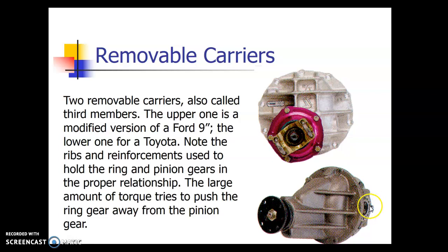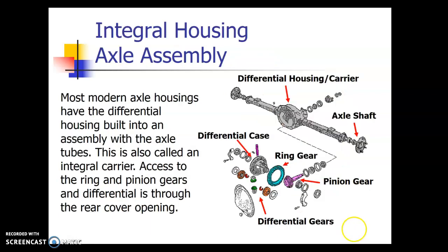Basically right here is where the axle comes in. This whole section can be unbolted from the axle housing, and then this is where the drive line comes in. This whole section comes out. It has that carrier setup and a ring gear and pinion all in it, so you can set it up on a bench. Really popular among rock crawlers and racetrack folk, because it's easy to set up on a bench and you can drop it in, drop it out, hence the name dropout.